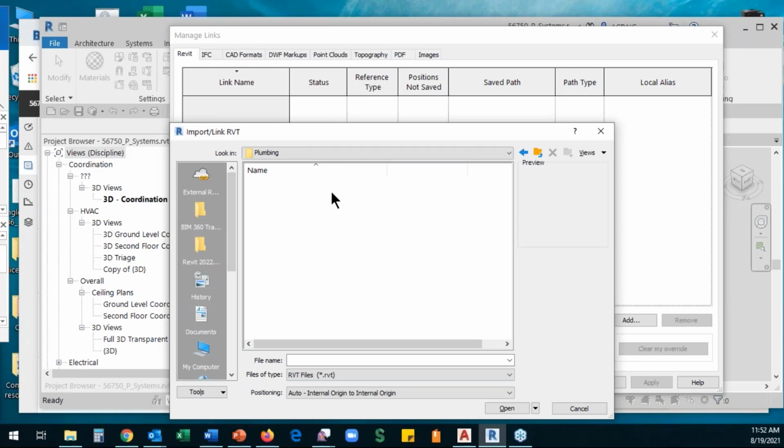That consumed folder gets populated when someone from your team goes in and looks at the shared model and says, yes, we want to consume it, and it will place it into your folder. The nice benefit with that is that when you're working in your team's folder, you don't have to go out of it looking for models, and it will automatically update only when someone on your team designates that you're ready to consume it.